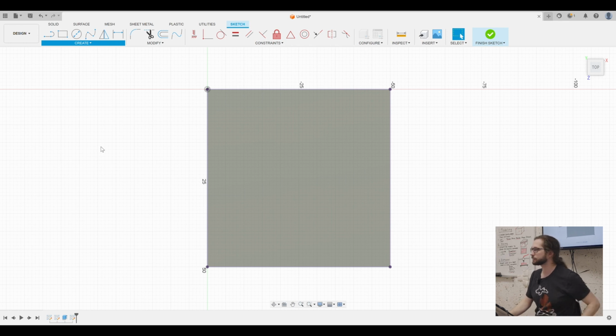So when we say project, does it mean project to or project on? Yeah, so you are taking whatever object you have selected as the project in the project function, and you are projecting it onto your two-dimensional drawing plane. Okay. So the idea is if I have a cylinder, and now my plane is here, if I project that, what I'll actually end up with is a rectangle.